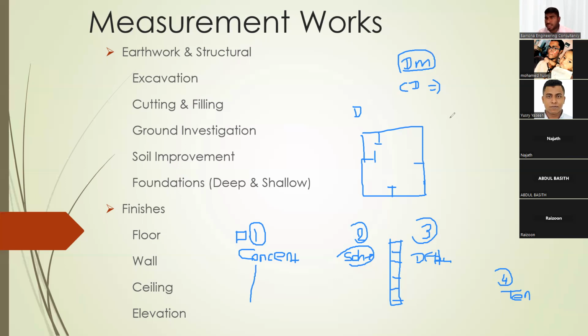So they make sure that the building is livable, the health and safety. Because when there is a fire, that's health and safety. Civil defense is the one that comes to tackle the fire situation. So civil defense is responsible to make sure that your building is safe to live in. So in the same stage, you submit your drawing to civil defense. Civil defense will review, then they will confirm to you that the building is safe to go ahead. So that is the second approval you get. First, in Dubai, the municipality. Second, you get from civil defense.